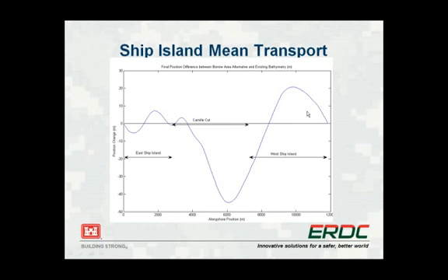Here's the final position difference. There is about a 50-meter or 45-meter position change between the bathymetry with the borrow area, or the bar area, and the bathymetry without it. And if we hadn't used an external wave model, that change wouldn't be visible or present, because we would just assume straight and parallel contours all the way from the wave station into shore.